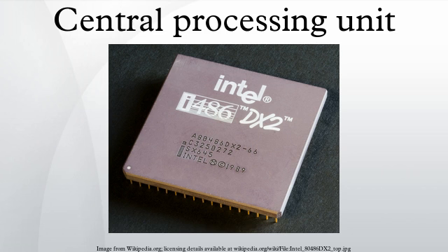By calculating the maximum time that electrical signals can move in various branches of a CPU's many circuits, the designers can select an appropriate period for the clock signal. This period must be longer than the amount of time it takes for a signal to move, or propagate, in the worst-case scenario. In setting the clock period to a value well above the worst-case propagation delay, it is possible to design the entire CPU in the way it moves data around the edges of the rising and falling clock signal. This has the advantage of simplifying the CPU significantly, both from a design perspective and a component count perspective.